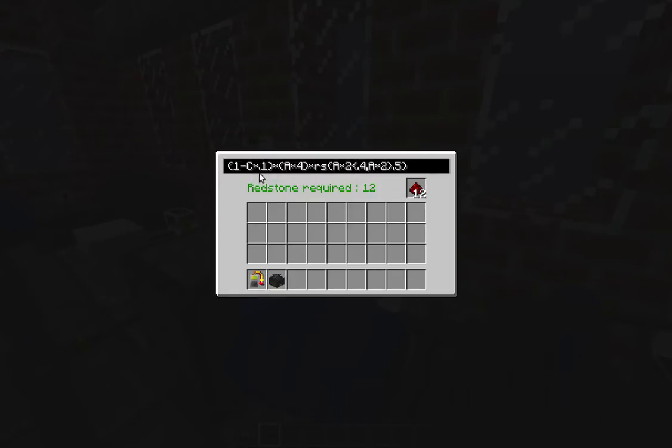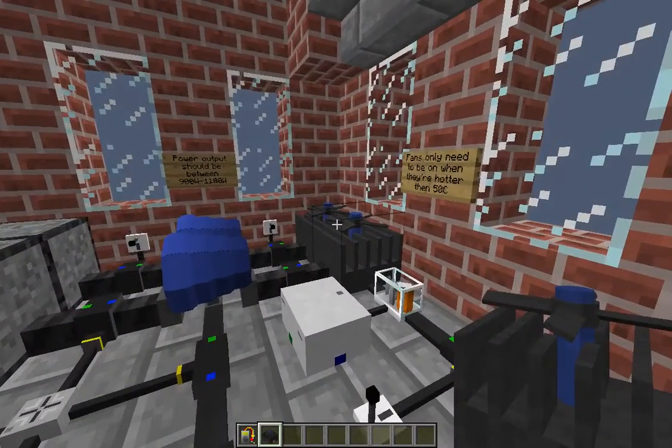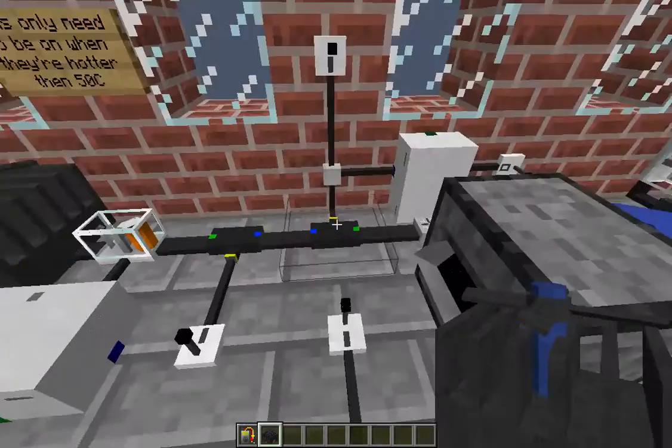The key to multiplying these comes in if your voltage is about average, but all of a sudden your temperature spikes. Then that's going to be about 50. That might be 0.75 or something, and that's going to get larger and cause your furnace to start cooling more. Again, all these coefficients like this 0.1 and this 4 here are up to you and your demands. But the neat thing is that you can actually say, only cool this when it needs to be cooled, but do it efficiently.